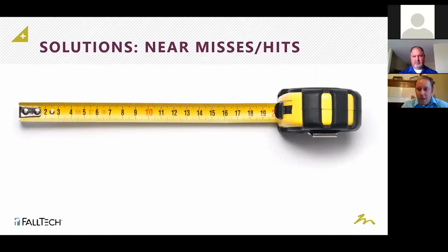But it wasn't the PPE that caused the incident. The PPE, keep in mind, doesn't stop the incident from happening. All it does is reduce the severity and the potential impact of that incident. If we were going to stop that incident, we had to look and think about the objects up above, and how a tape measure, as an example, on a belt that we've all dropped if we've worked in construction or done any construction, could become a lethal weapon or a lethal object at height. And so it's that kind of planning that's truly going to be proactive and prevent incidents.